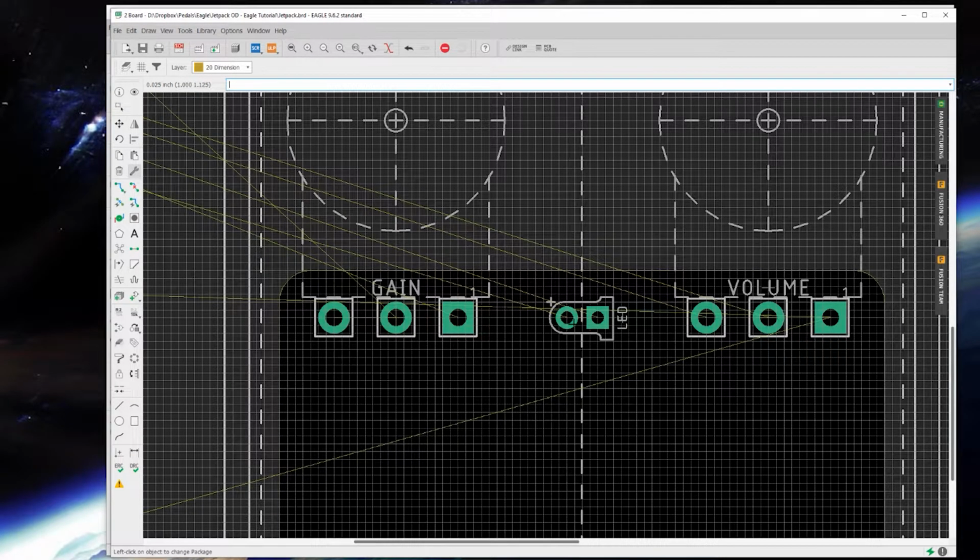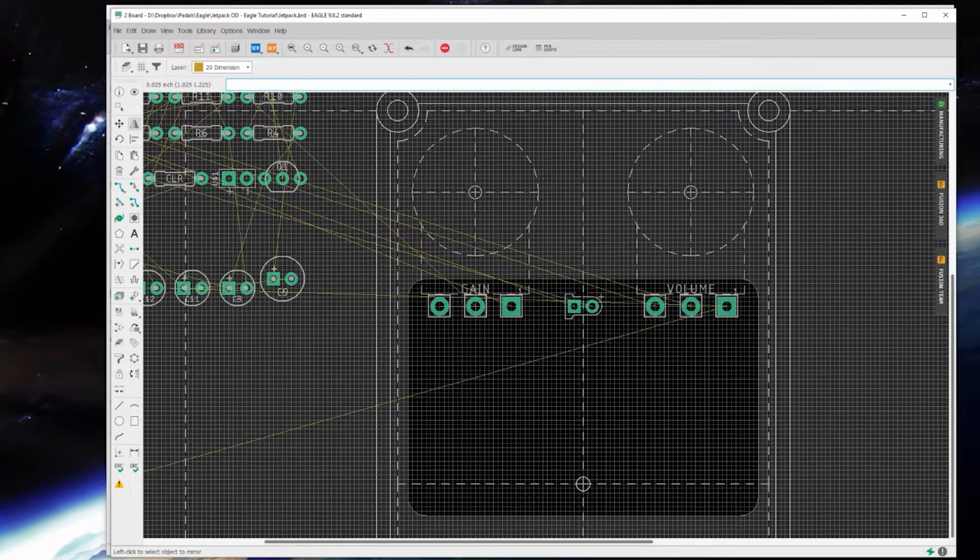And this is on the top layer of our silk screen, and we want this to be on the back because that's where it would be populated from. So I'm going to go to the mirror tool, which instead of just flipping it 180 degrees, flips it along the y-axis. It flips it to the back. So now, since we've turned off the names of the back layer, that is gone, and so that should be on the back silk screen, which, since there's no traces laid down yet, you're just seeing straight through.